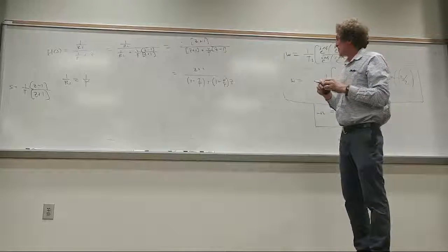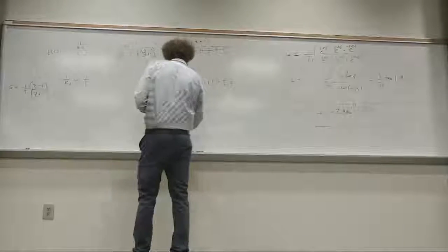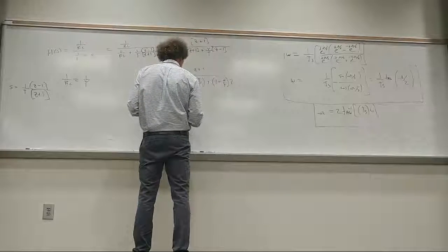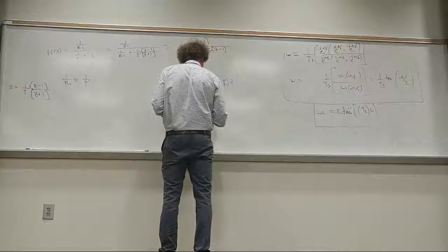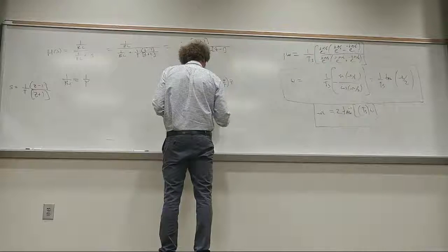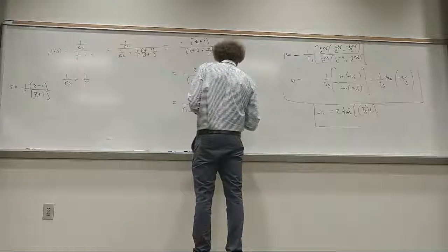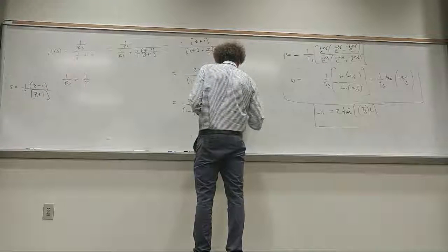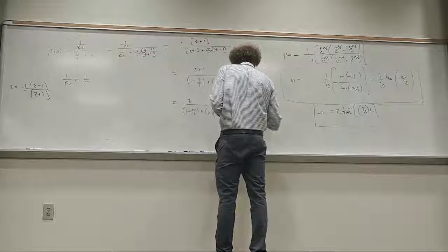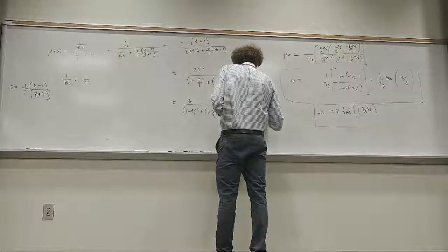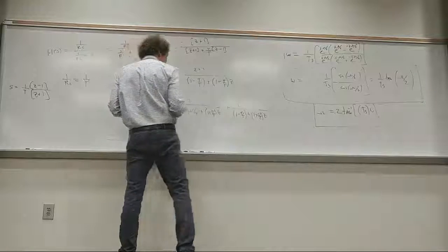Now, this can actually break down into two functions. I get z over 1 minus tau over T plus 1 plus tau over T times z, plus 1 over 1 minus tau over T plus 1 plus tau over T times z. And this is now my H of z that I could implement.